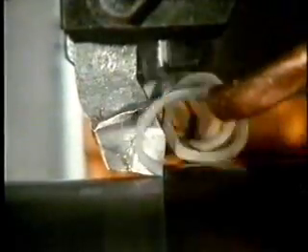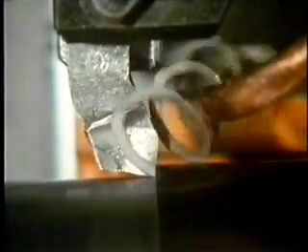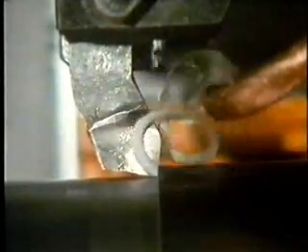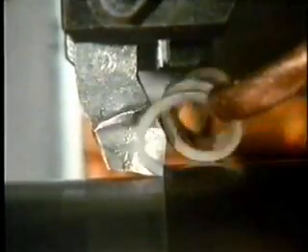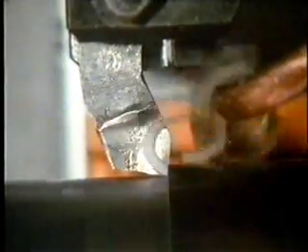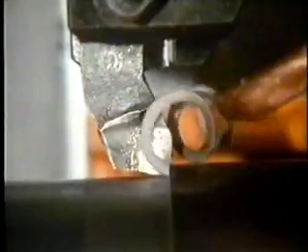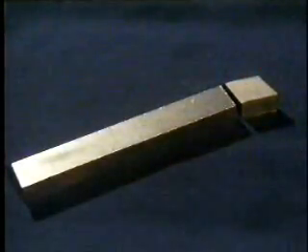High-speed steel derives its properties from alloying elements like tungsten, chromium, and vanadium. The most common ratio is 18 parts of tungsten, 4 parts of chromium, and 1 part of vanadium in 0.7% carbon steel. Because it's an expensive material, only the actual cutting end is made of high-speed steel. This is welded to a cheaper carbon steel shank. Flash butt welding is often used.